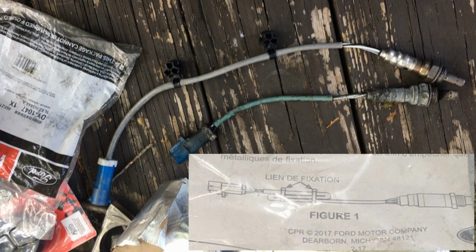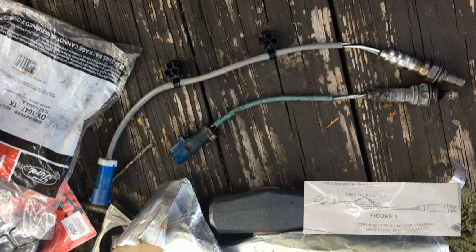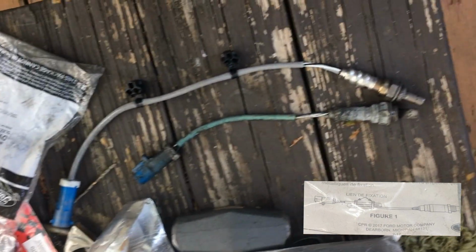So in this case, you have to shorten the effective length of that harness. I think the correct way, as I understand, is to use some zip ties and fold the wire to shorten that effective length. Some oxygen sensors come with those instructions, but the oxygen sensor that I got didn't, because I didn't get the right one for this particular model of car. But it will still work. And again, this is kind of sloppy, but I was in a hurry at this point because it started to get dark, and I wanted to confirm that this new O2 sensor was going to resolve this issue.